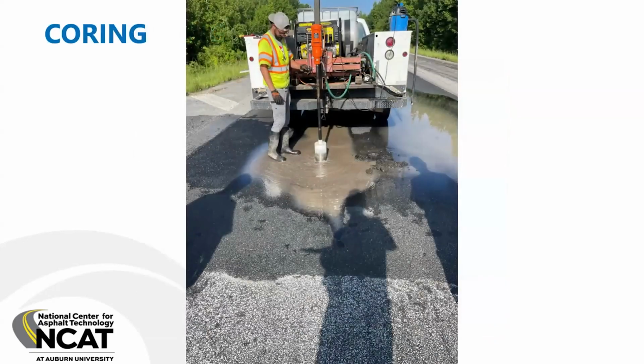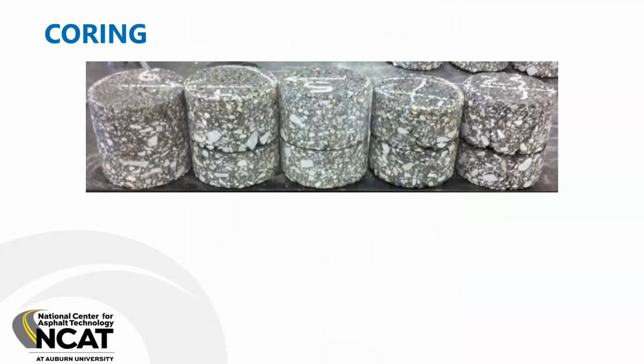And then last but not least, the tool we often use is the coring. I would say this is probably a pavement engineer's most useful tool. You can learn so much by pulling a core, but of course it is a destructive test. So looping back to what Buzz mentioned earlier on one of those test track sections, you can see from left to right how this progression of distresses proceeded through these cores. And so we took multiple cores over the section of pavement, trying to isolate and find that crack at different points of both initiation and propagation.